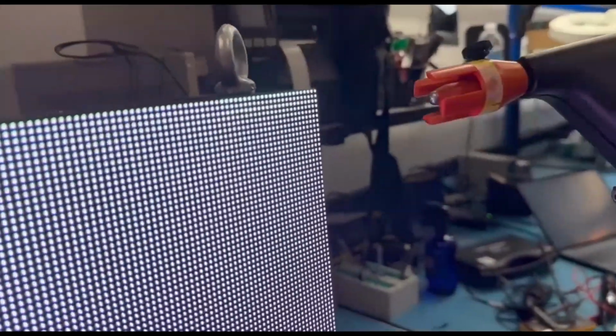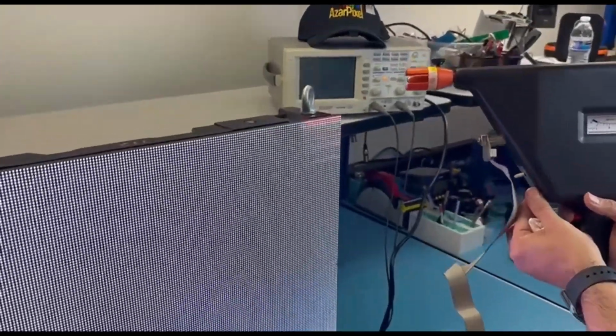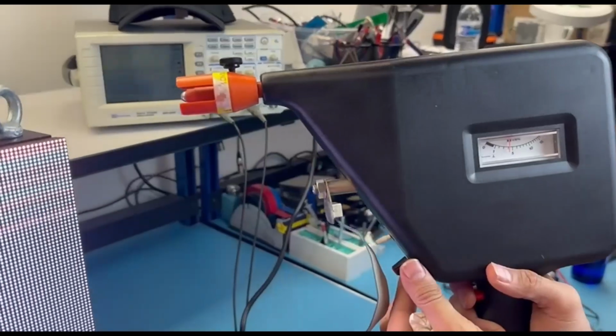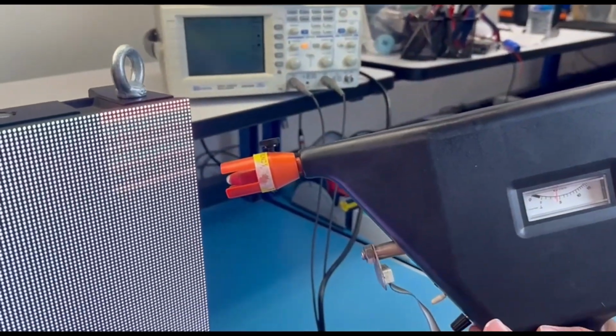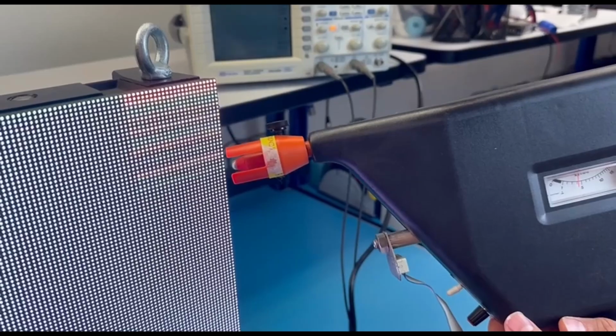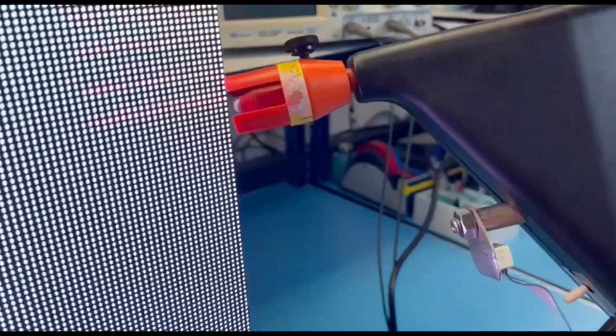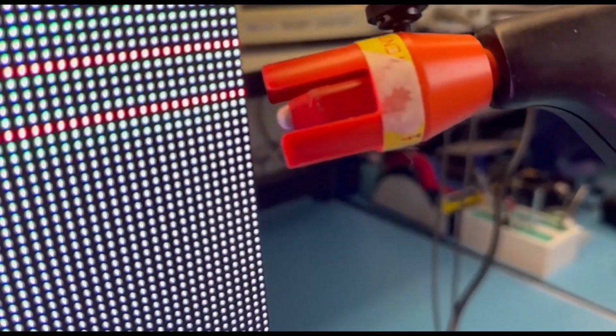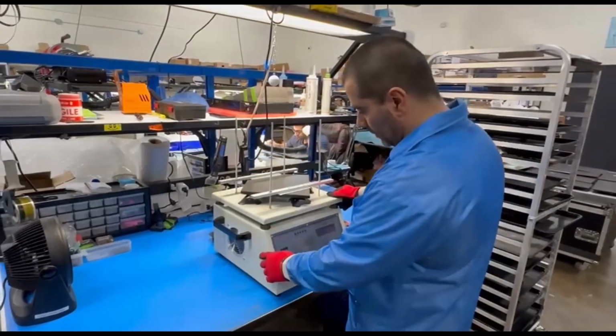The LED module managed a 1 kV electrostatic discharge well, showing its resistance to moderate static electricity. However, when exposed to a higher 2 kV discharge, the panel's IC drivers burned out. X2V still meets basic requirements. Let's look at the vibration test.